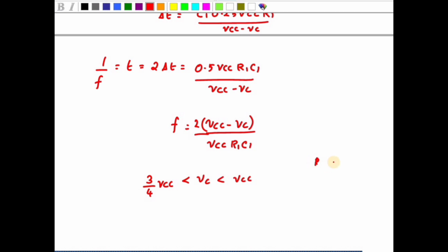Here R1 ranges from 2 kilo ohm to 20 kilo ohm, and VCC is plus or minus 5 volt, or it may be plus and minus 12 volt. This VCO is commonly used in converting a low frequency signal such as EEG, EKG into audio frequency ranges.